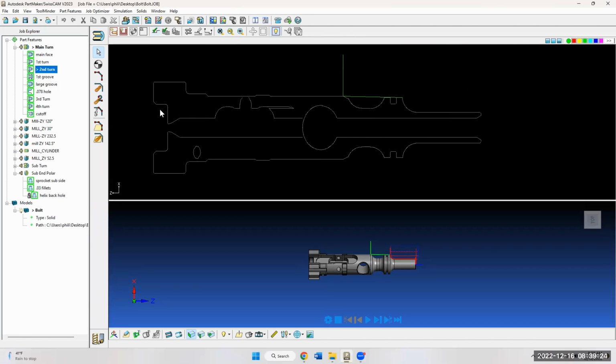Follow that up with a second turn. Again, I'm trying to make sure that my tool pads are not greater than the length of the guide bushing, until I can get into an area where I know I don't need to draw the bar back, then I can start making longer turns. I can also put the machine into support function if I wanted to do a long turn and use a sub spindle to support the part. I'll be doing that for the back end here.